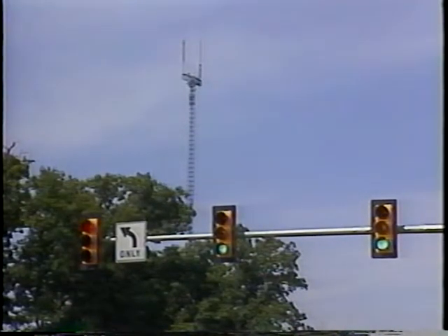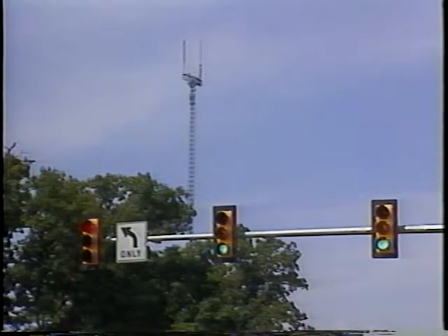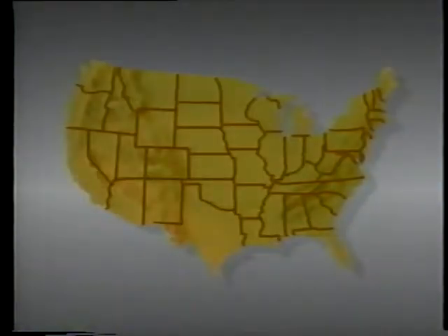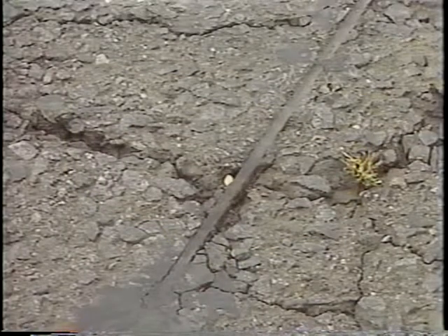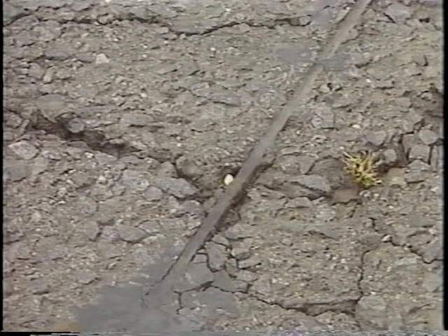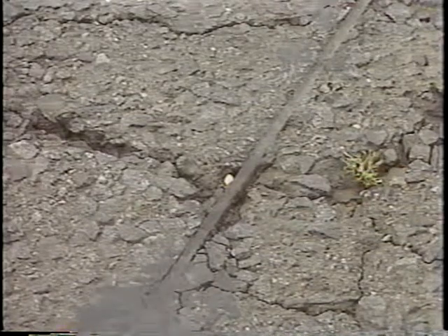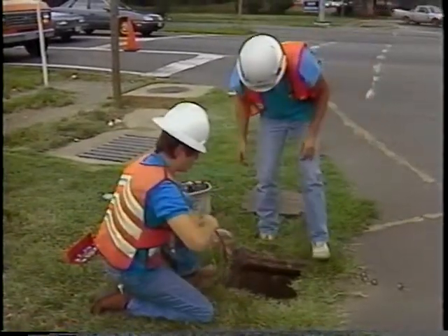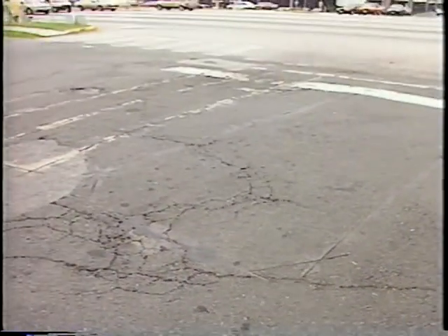Long-term effective operation is the goal. The large number of loop detector failures nationwide has created a deep concern within the traffic engineering community. A number of studies have traced many loop detector failures to a problem with the in-road loop wire, or to the splice between the lead-in wire and cable. These failures are usually due to bad pavement conditions or sloppy installation techniques.